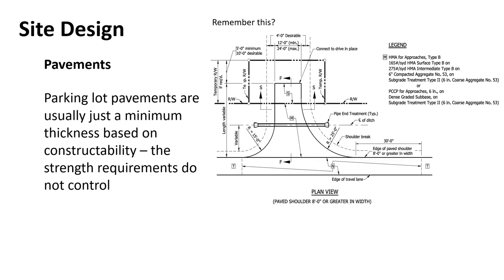It's not strength. In concrete, what you have to worry about there is thermal cracking. Right? If your concrete pavement is too thin, it's going to buckle and it's going to warp and crack, right? And that's a serious problem. So you need a certain depth of concrete to just be structurally stable on its own, even without cars driving on it. And again, it's not going to be the strength issue of the weight of the cars driving across it. It's going to be its own internal forces. It has to balance all that.